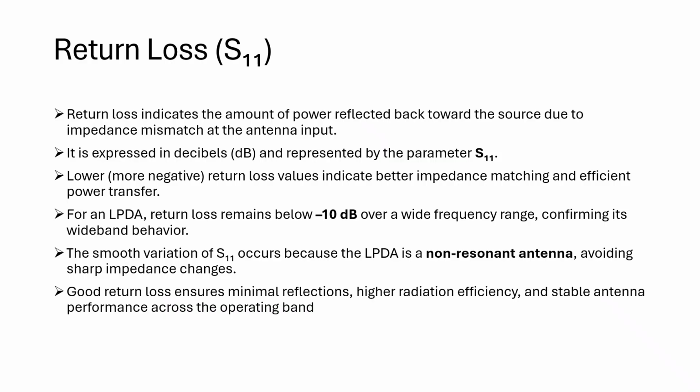The first parameter is return loss. Return loss represents the amount of power reflected back due to impedance mismatch. In our design, the return loss remains below -10 dB across the operating band. This confirms good impedance match and efficient power transfer.